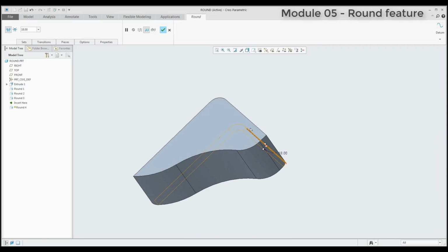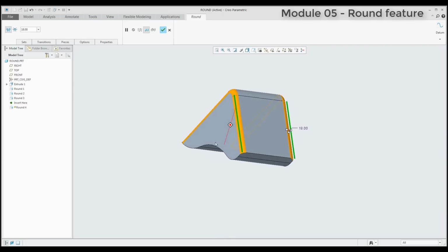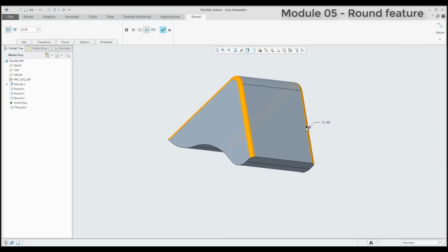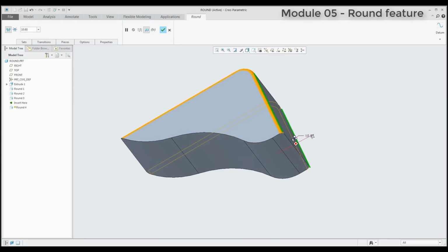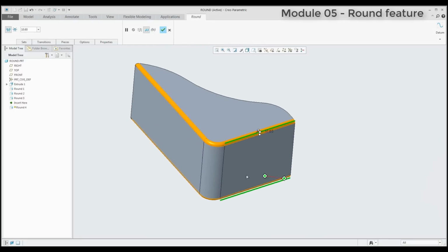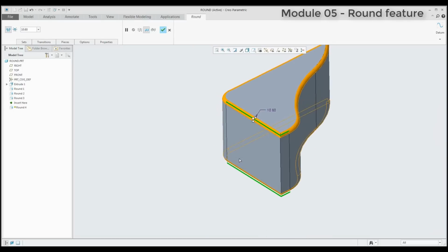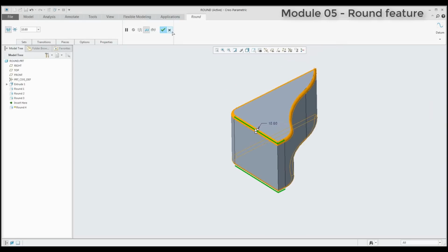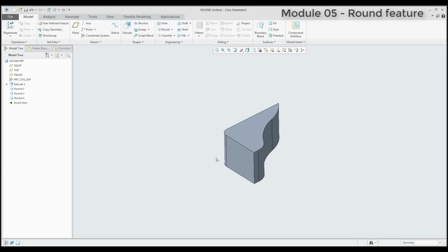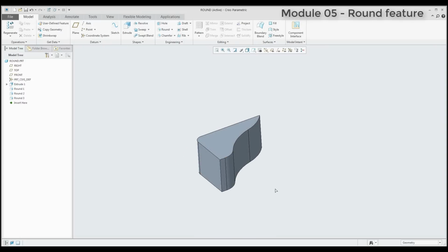Again, on the opposite side, with the control button, I will select another edge, and the system will drive these edges. Okay, but the question is, if we would like to continue and go through the whole shape, again I will select with the control button and it's done. So right now I have selected 4 edges, and the system will create the correct shape for me. The question is if it is possible to specify the shape on one selection.